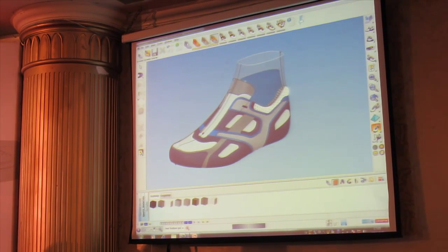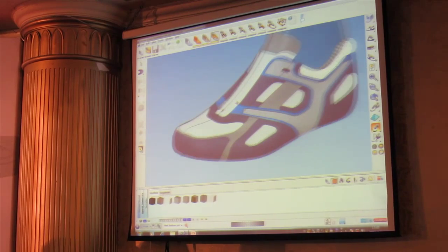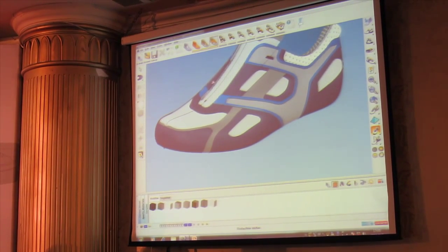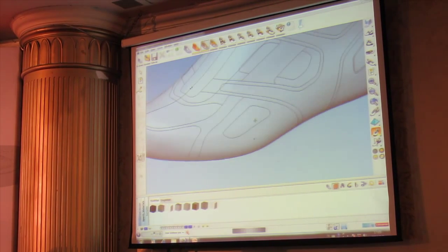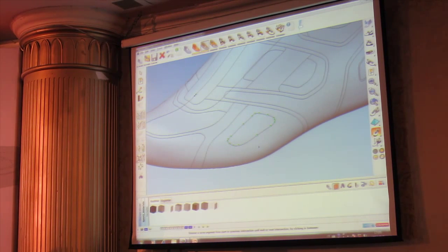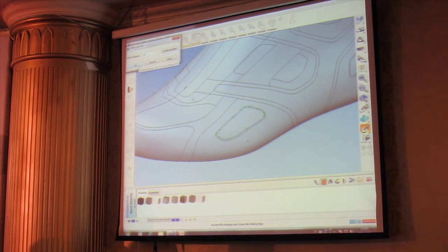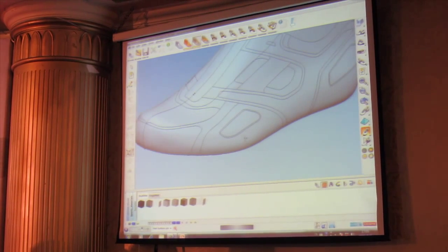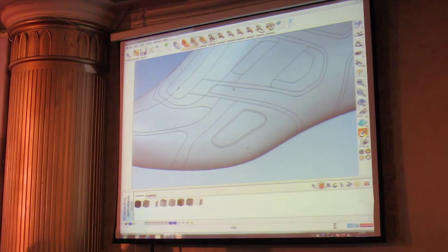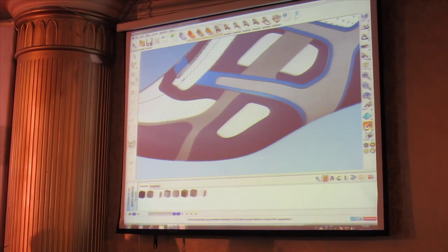Okay, so all of my shoe pieces have been created. So the next thing we'll do is move along in the activity lists to stitches. Now I can create stitches in a couple of different ways. The first method I'm going to use is by creating stitches from an offset curve. So I've just come back to the curve that I created initially and made a 1mm offset.